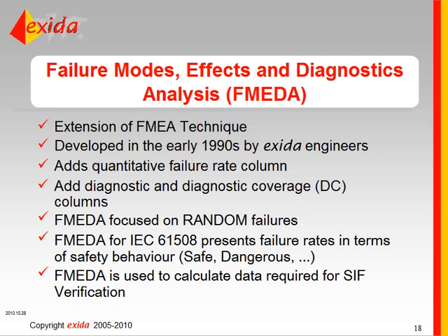And so this FMEDA is then used to calculate the items that are required by the standard for each product, the quantitative items, which is specifically the safe failure fraction and probability of failure on demand.